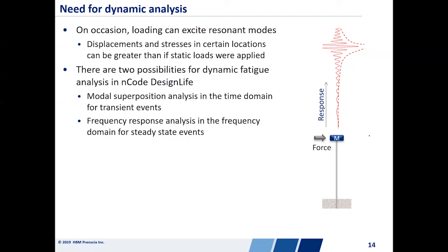These increased displacements and stresses can be far greater than if we had made static assumptions. And these high levels of stress are really what's going to be driving fatigue. Therefore, it's really, really important. We have to be careful when we determine if our structure is responding statically or dynamically, and then apply the correct methodologies in FE to be able to capture those dynamic effects if it's necessary.